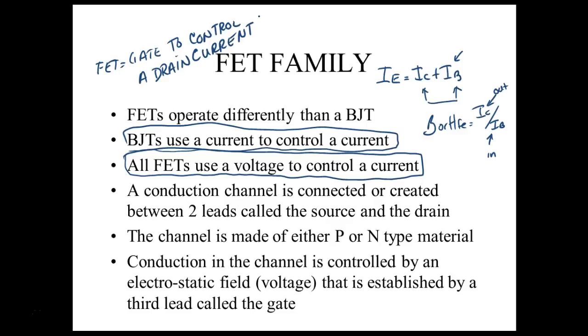In fact, just looking at the FETs and the packages that they're in, they're going to look exactly like a BJT. So this is where the partner will come in, and we'll also show you how to check the FET with an ohmmeter. In fact, I think I told y'all in the other class that one of the transistors that I gave you that everybody said was bad because it was not a BJT, it was an FET. So in actuality, the transistor itself was good, but I wanted to give you something that appeared to be bad.